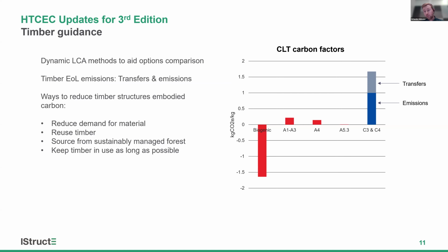Timber guidance, we've acknowledged that there are dynamic LCA methods to aid options comparisons, and this really helps when we compare timber and steel and concrete. We have this biogenic carbon value for timber that it's not very clear how to incorporate into the general comparison. If you want a bit of a hand with doing that, then dynamic LCA methods that the RICS guides describe can be used.